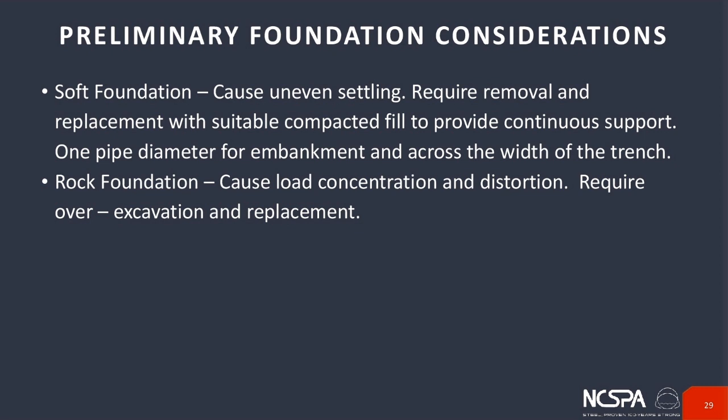Sorry, one other thing I wanted to mention is you do get the occasional situation where you have a transition between the two. When you do get that, you want to take special care to make sure that you have uniform support across there, because you could get some differential settling in the pipe due to the rock in the soil.